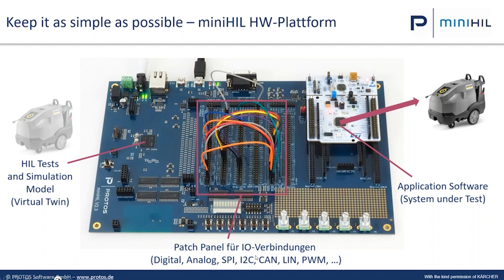Here you can connect this with the typical low-level IOs like digital, analog, all the low-level bus systems, CAN, LIN, of course, PWM, and so on, UART, etc. So now the main effort is not to connect the hardware. That's why we have the mini hill board that works out of the box mostly. So the main effort is to create an environment simulation your software can live in, and the test cases.